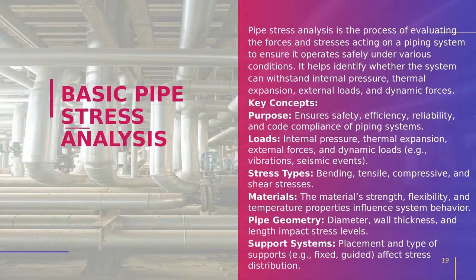So whether we go for general arrangement, isometrics, or even fabrication, before that we should pass the stress analysis. After preparing the basic general arrangement drawing, we have to do the stress analysis to check whether it is passing our code and everything is within limits. Then only we will go for the final general arrangement. Then only we go for the isometric drawing.